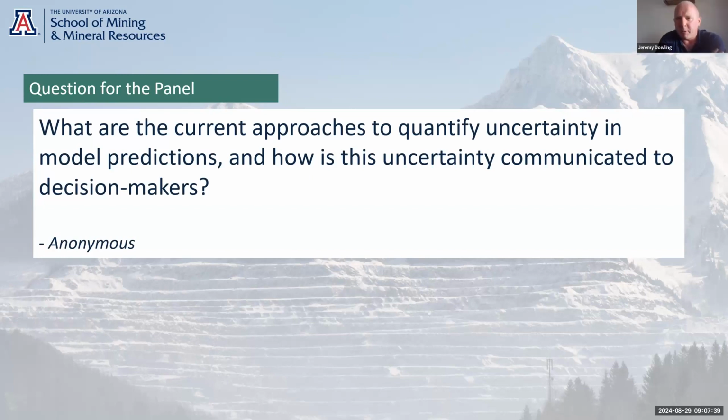Yeah, I think in terms of pit slope pore pressures, the biggest uncertainty, or the factor that causes the field conditions to greatly deviate from predictions, can be the geologic or the hydrogeologic uncertainty, and the uncertainty in the hydrogeological parameters, which are often considered in classic groundwater modeling uncertainty analysis: what's the uncertainty in my K values or my storage values?